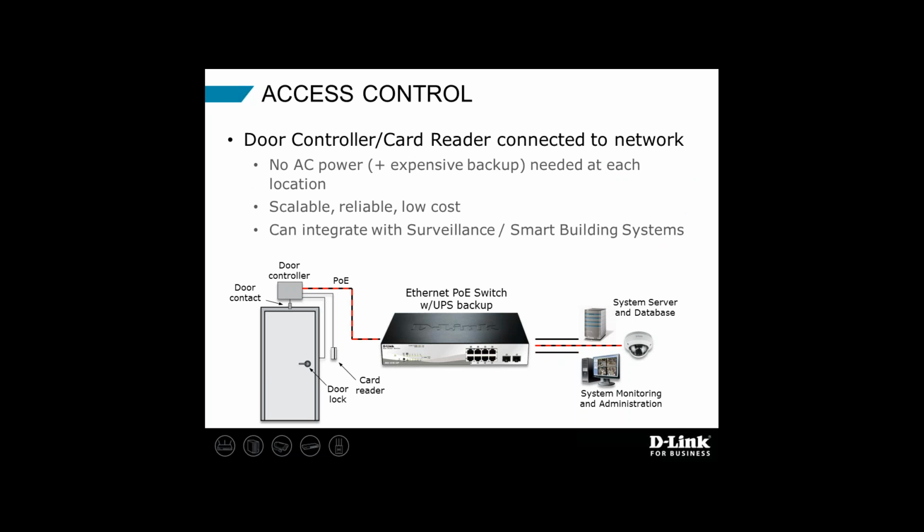Here's one, access control. Quite often you've got door controllers or badge readers or card readers that can be POE powered, and there's a lot of benefits to doing that. If I don't have POE powered door controllers, then I've got to get AC power out near that door, and I need probably pretty expensive AC power backup. In the event of a power failure, I still want to be able to operate that door. That can cost a lot of money.